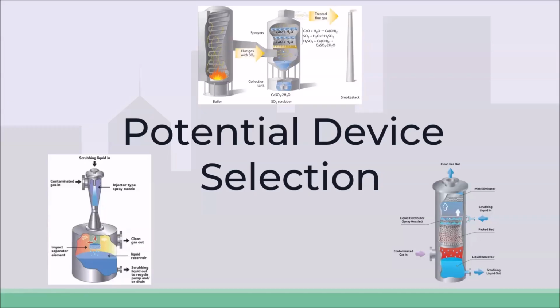Next, I'm going to provide an overview of flue gas removal, explain the benefits of using each device, and compare the three major scrubber types that we have chosen, those being the packed bed scrubbers, Venturi scrubbers, and spray towers. To meet these goals of efficiency and productivity, wet scrubbers are commonly used because they bring flue gas into contact with a liquid, often water or a chemical solution, to absorb gases and capture particulates.